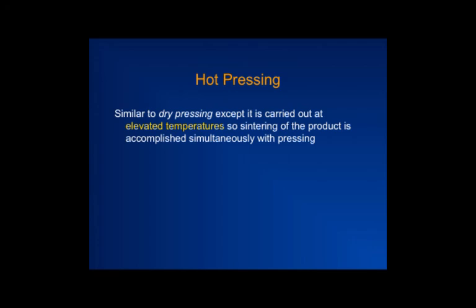What happens to mechanical properties as you raise the temperature? Okay, so material softens, because it's the same as a blacksmith heating a piece of iron and then hitting it with a hammer, right? As opposed to just hitting it cold. Deformation can happen at higher temperatures more easily than at lower temperatures, and you can get higher densities.